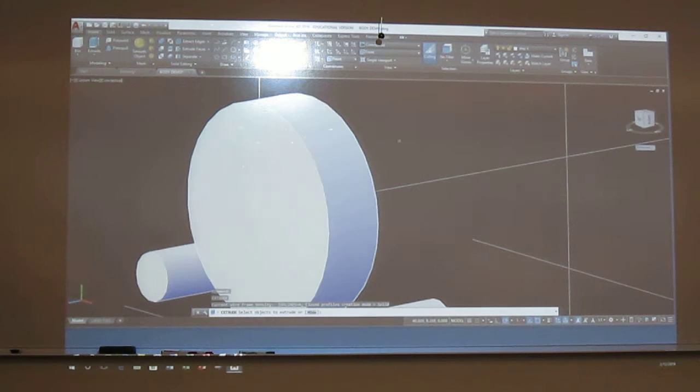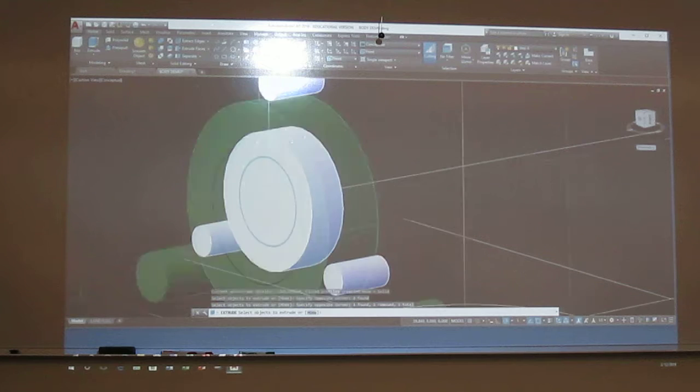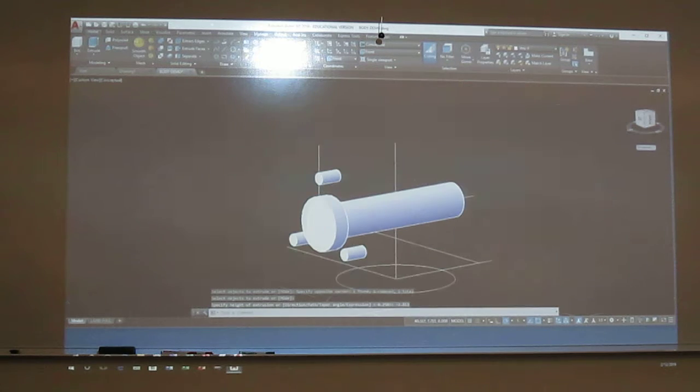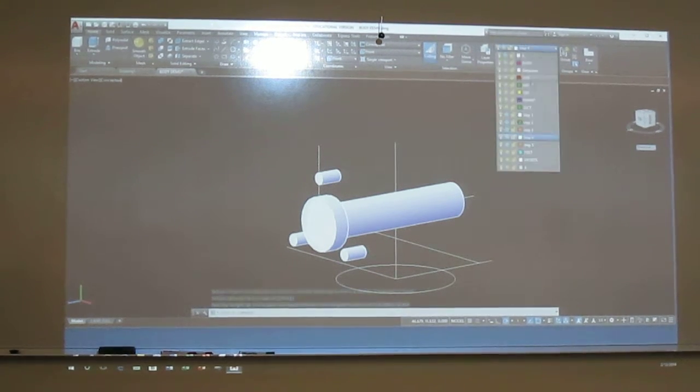And then I've got one more on here, this middle one. I try and get it selected. I'll just select all of it, deselect my model, it leaves me with my circle. And I'm extruding this one minus 2.813. Okay? So I've created all those negative shapes. Now I'm going to turn my model back on.